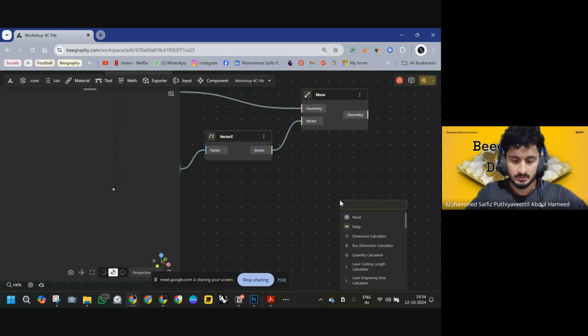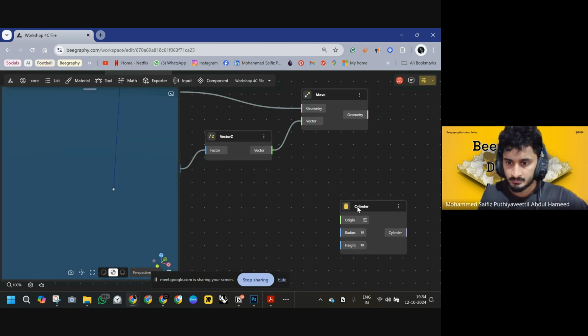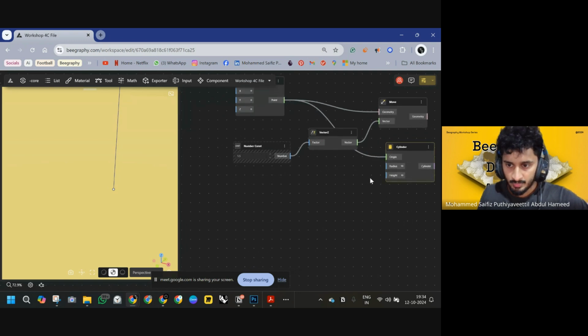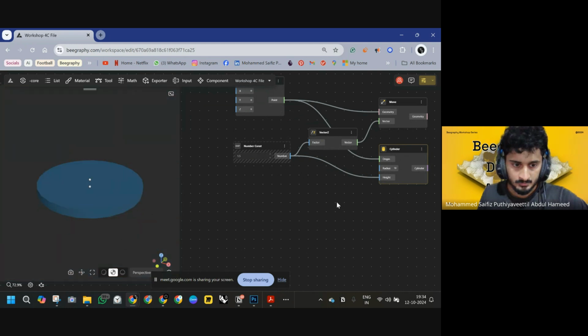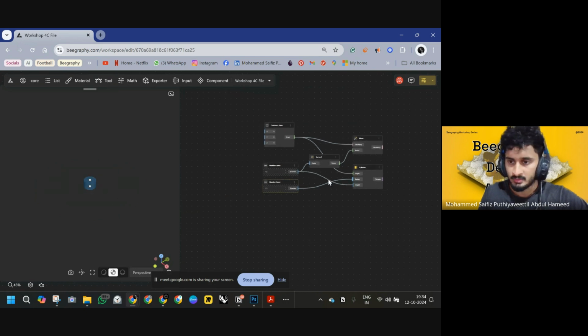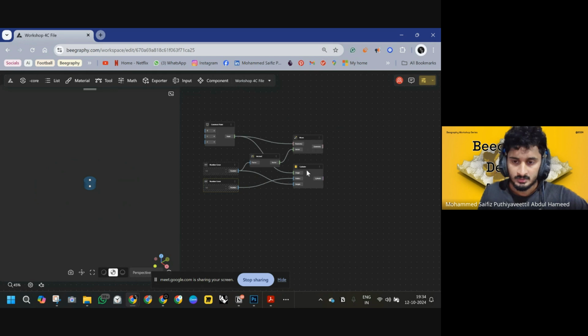And then we'll also do a cylinder on the same point and the same height. Now we also need to select the radius for that non-slip base. We can give somewhere around, let's say 1.2. Okay, so we have that point. Now this is step 1.